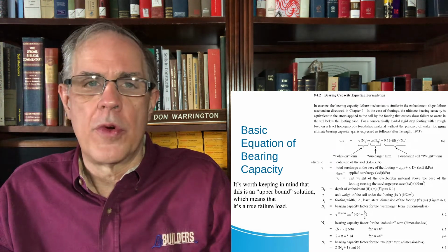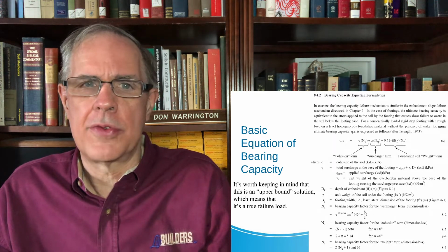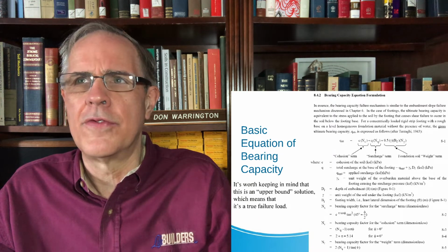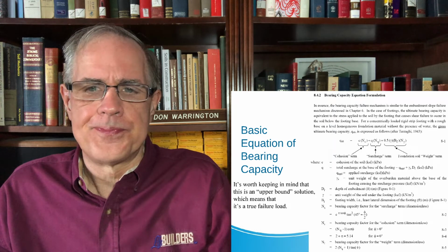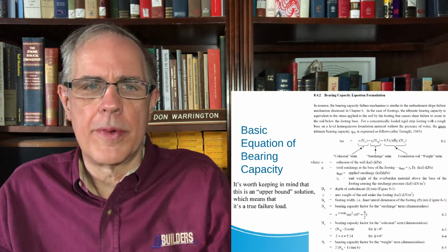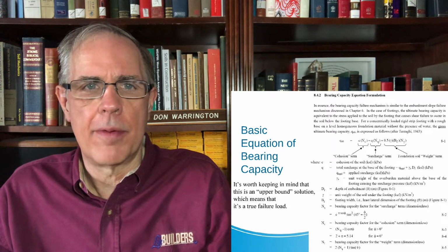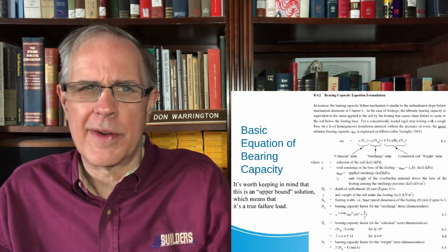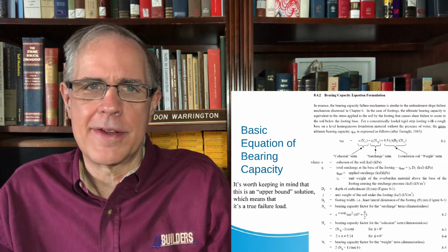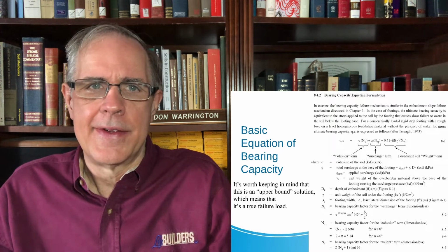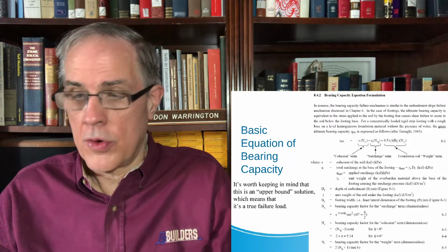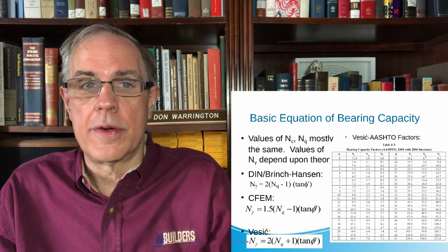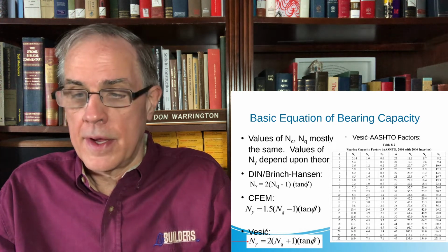And for the Terzaghi solution, Terzaghi was the original one, and it goes back to the 1930s and 40s, when he added the last term and solved the problem. The first two terms, the N_c and N_q, pretty much everybody agrees on those. N_gamma is one of those things that geotech hasn't quite settled down on. So it depends on whose theory you adopt.